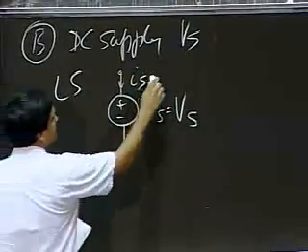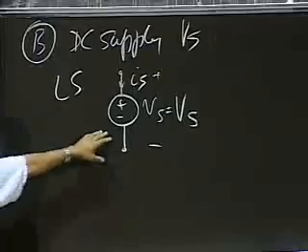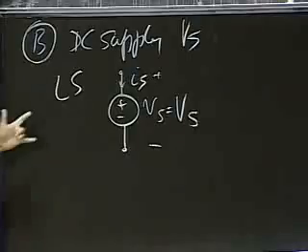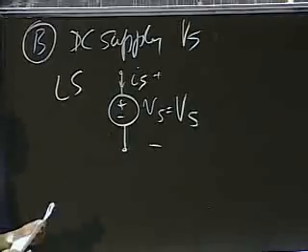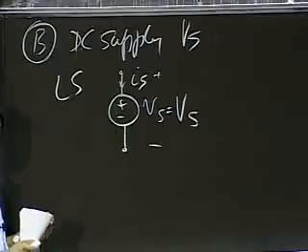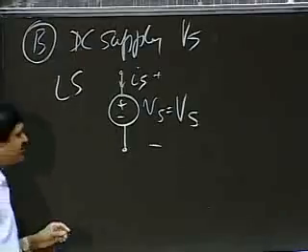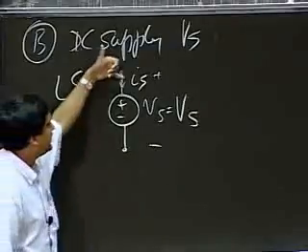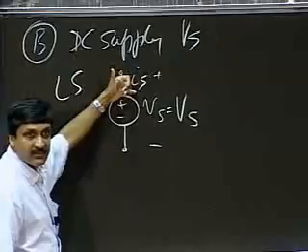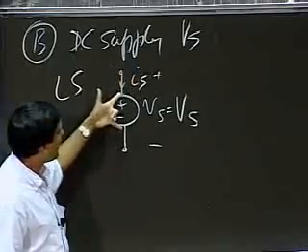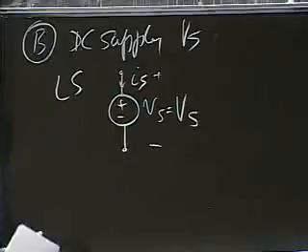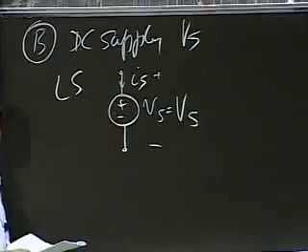The element law for a voltage source is Vs equals some capital Vs. It's a constant voltage. So what do you expect to be the small signal model for a voltage source? In other words, suppose I have a small change in the current. By how much should the output Vs change? It shouldn't change. It's a voltage source. So what does the intuition tell you is the small signal model for a voltage source?